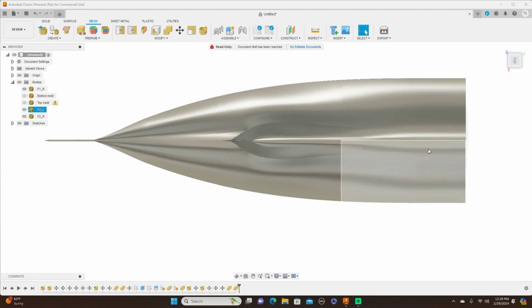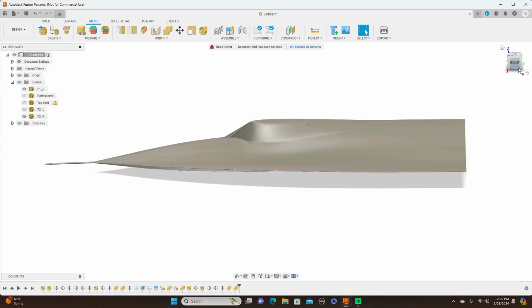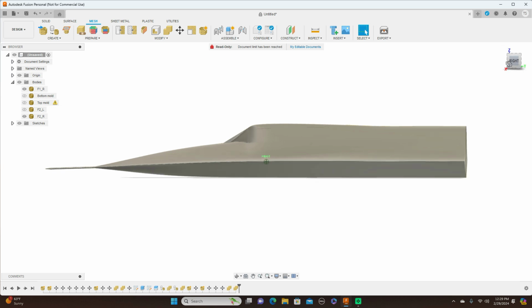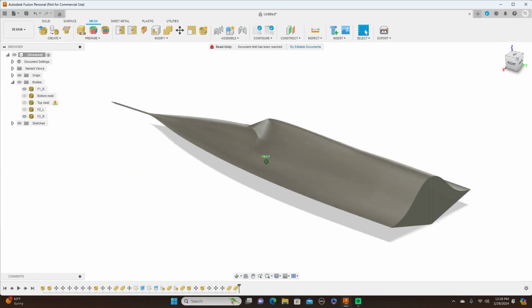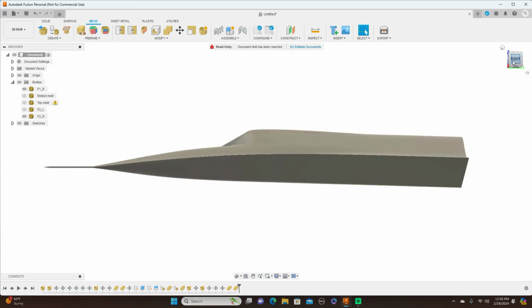All right. There. Now I turn this, and they both, yeah. There you go. Once again, when you do that combine, if you want to combine, make sure it's set to join. If you want to cut, make sure it's set to cut. And as soon as I did that, I pretty much knew why they didn't combine. So now we have that.